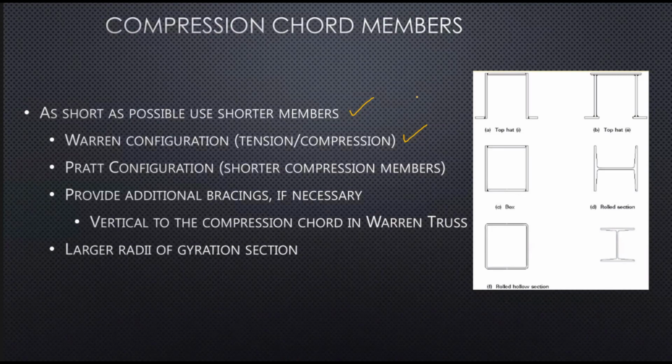Now, when you do the topology of the truss configuration for bridges, you must see how the members are added so as to reduce the compression effective length, right? Usually because the compression is governed by the Euler buckling stress or governed by buckling beyond a point. So primarily, we are always worried about this. These are the typical sections that we use for compression members, right?